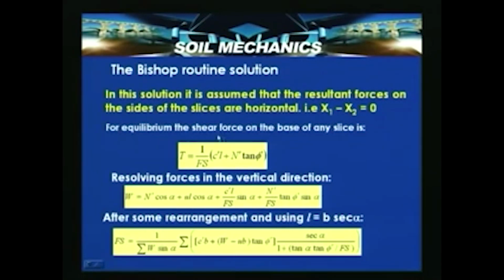So, for equilibrium, the shear force on the base of any slice is T equal to 1 by Fs into C dash L plus N dash tan phi dash.